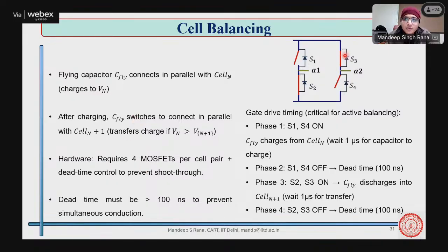Even after that, you are working with a full bridge circuit, which is an inverter circuit, and we cannot turn on two switches within one inverter leg together. So what we need to do is run one pair of the switches, which connects your capacitor to charge. Then we have to wait for some time before we turn on the other two. Like we will first close these two and then we'll sit there. That sitting time is called dead time or dead band.